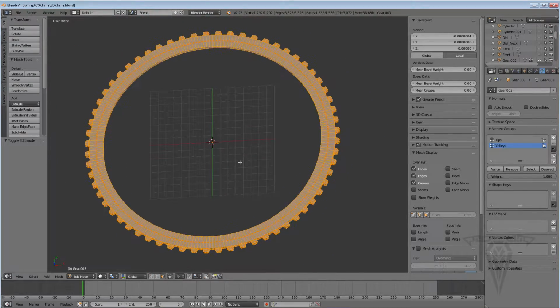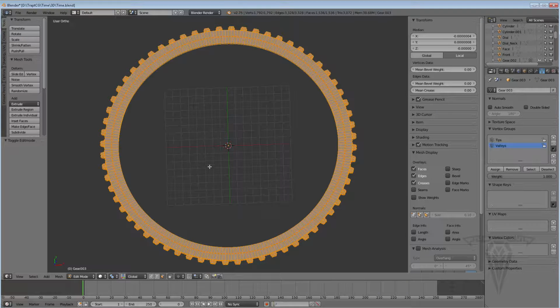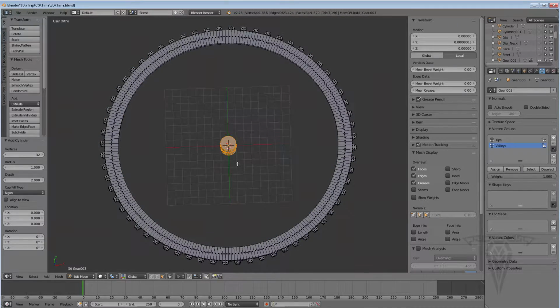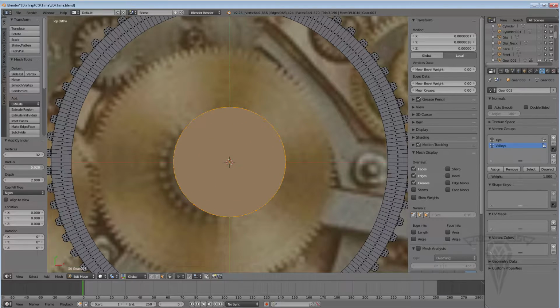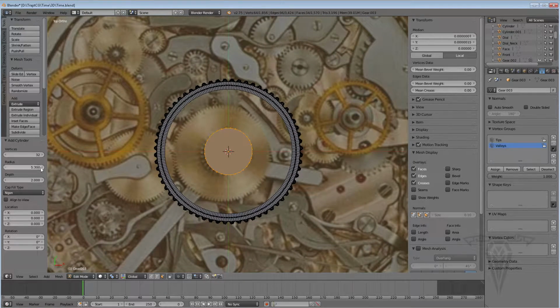Now, if I create an object in edit mode, it's going to be part of the first object I created. So like I said, edit mode, Shift A. Let's go down to cylinder. Okay, go back to my top view. So my cylinder, I'm going to increase the radius. Let's see, maybe a little smaller, let's say 5.